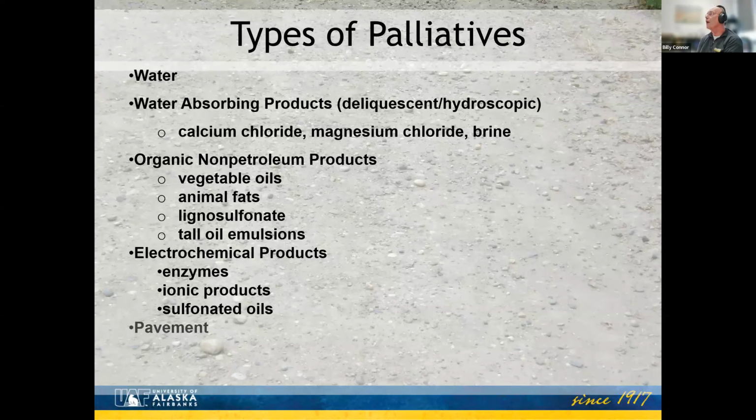So we've got that. And I see a question, have we heard of using lime on roads? Yes, people have used lime on roads, but they work best if you're using lime for clay materials. They don't work very well when you've got gravels and silts. So I would reserve those for clays. And what they do is they change the characteristic of the clay to be more like sand.